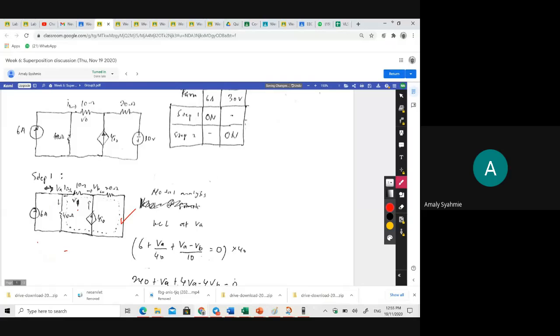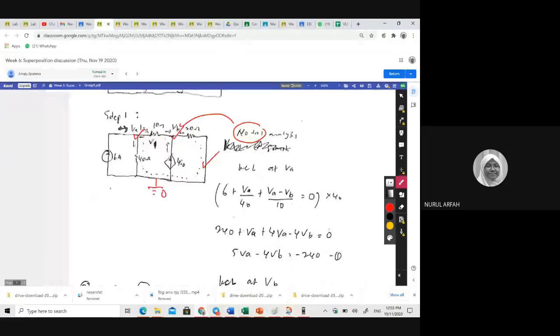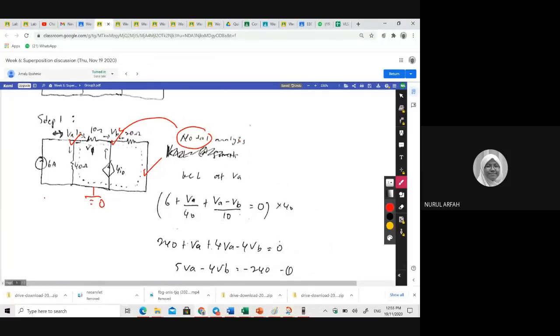So when I saw something like this, I straight away said that because you have the dotted lines here, this one is a mesh analysis. Because why? Because you don't have the reference point. Where is your reference point if you claim that you use nodal analysis? Yes, this one you label, then I can say, okay, still I accept it as a nodal analysis. Okay, all right.